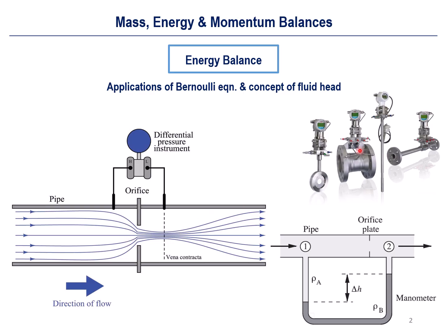So it looks something like this. We have the orifice here. As I said, it is a donut-like shape, and it can be inserted inside of these cylindrical pipes. And we have a pressure sensor here. There can be a variety of shapes of the orifice, but they share similar working principles.